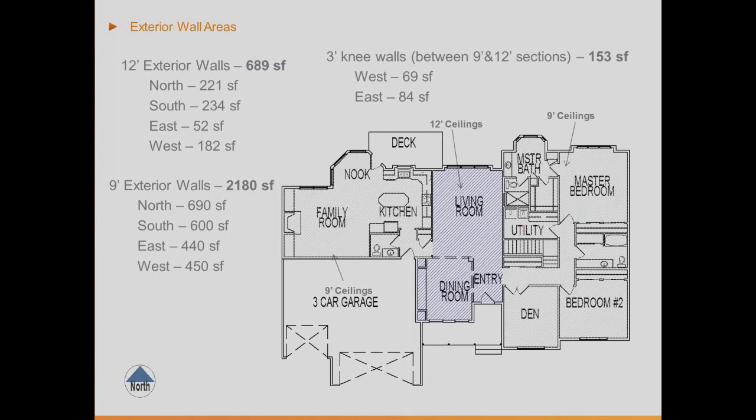And the knee walls. When you have knee walls, and this really is for the plan reviewers, you might want to show those separately, and you can actually double click on the actual wall that is shown and change it to knee wall instead of it just saying wall. You know, that's really nice for the plan reviewer. It just makes it quicker that they can go take a look at a REScheck and go, oh, that's the knee walls, got it. And even out on site when they have the REScheck report, when they're inspecting the knee walls, they might have a different insulation cavity R value than some exterior walls. And that's really important that you separate them out.